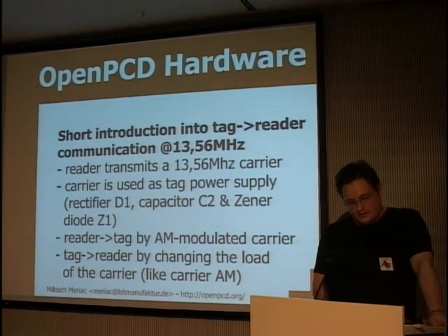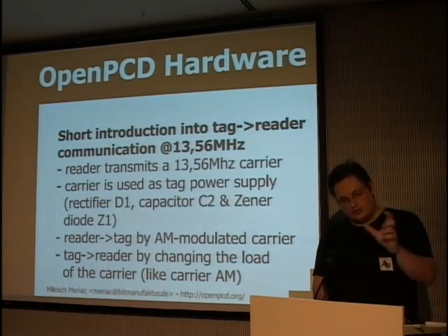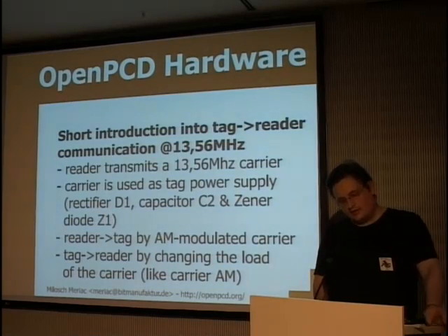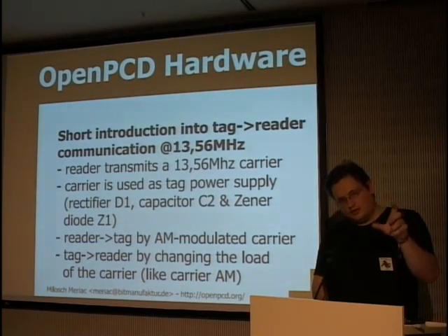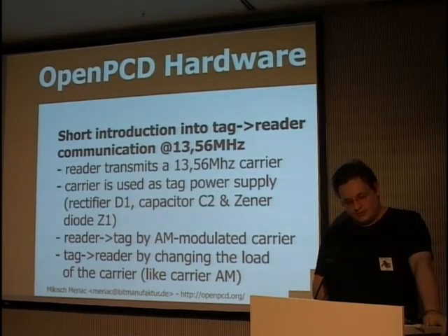The tag to reader communication is very hard to sniff currently because the load modulation introduces a small shift in frequency basically, and you can't sniff this easily because the dynamic range between the carrier and the data is pretty high. So the best approach to learn something about these protocols is to actively emulate such devices and try to find out what's going on.